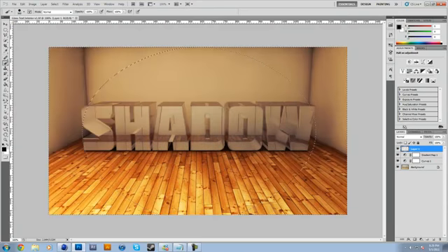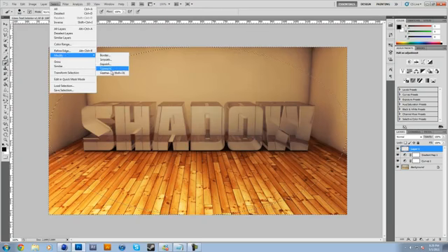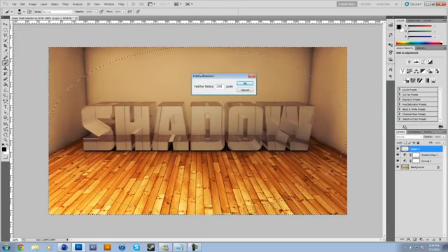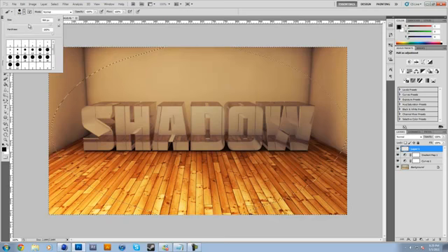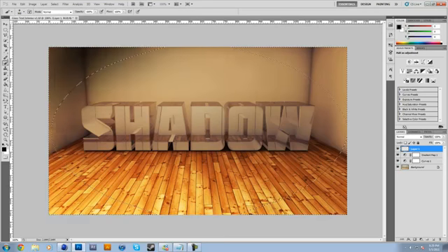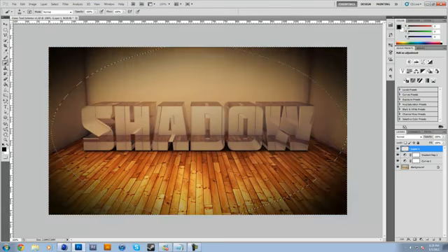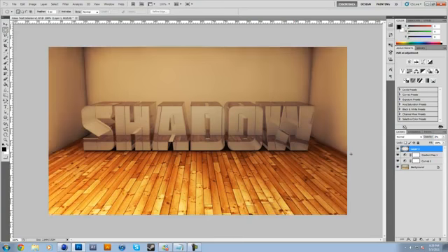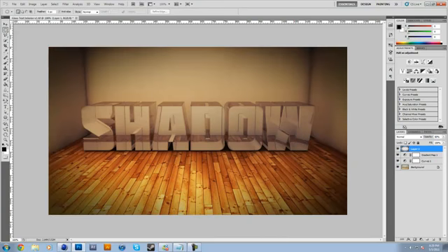Okay, we've feathered that way too much, so I'll take it back a bit and go feather, let's just say about 100 pixels. Also make this a soft brush, so we'll go around the outsides like this, and we'll deselect that. Maybe just take the opacity of that one down to about 80%, call that vignette.